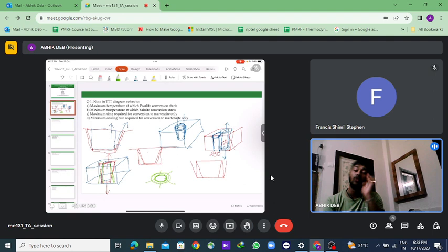See, there is a difference, right? Whatever the pattern is taking care of and whatever the riser is taking care of. After solidification happens, whatever shrinkage happens, that is taken care of by the riser. During solidification and in the liquid stage, whatever shrinkage has taken place, that is taken care of by the pattern. So you have to consider which part of the shrinkage you are considering.